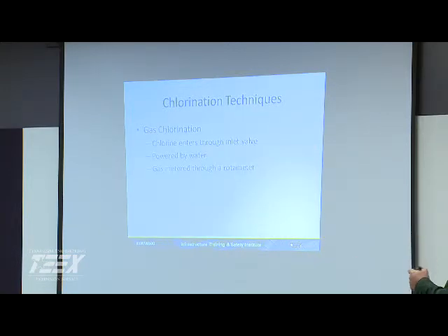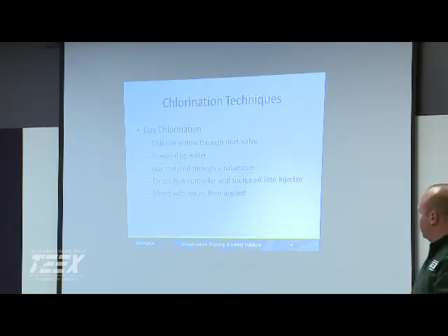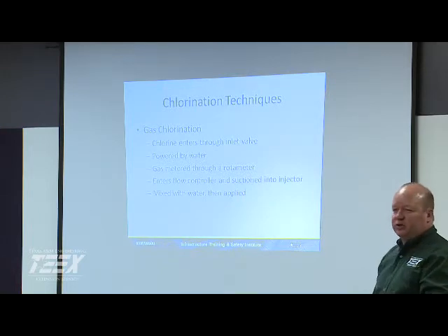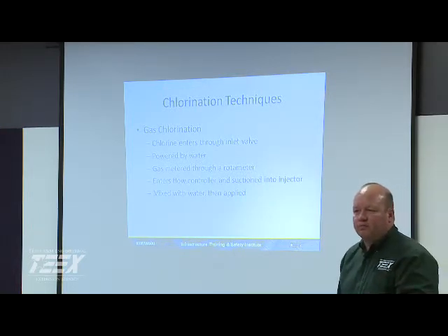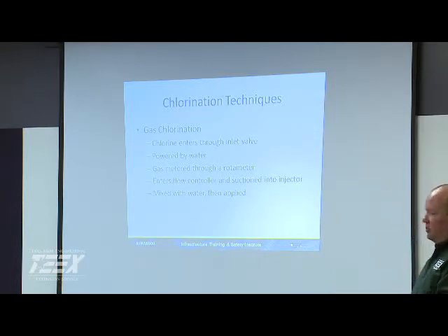Gas chlorination, y'all are at least familiar with using gas. You've got your water flow through there, you've got rotometers, that's where you're going to be able to tell what you're pushing. What are y'all pushing in pounds per day? I know you mentioned that earlier. Probably about 70 pounds or something. Okay. You have redundant systems, you've got a standby.